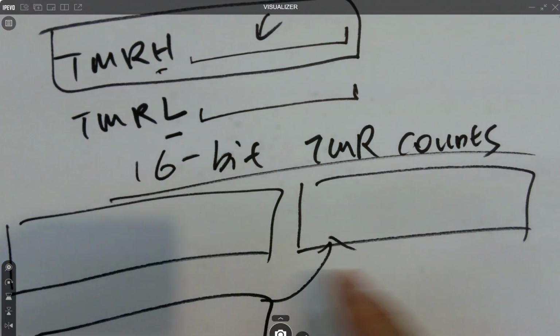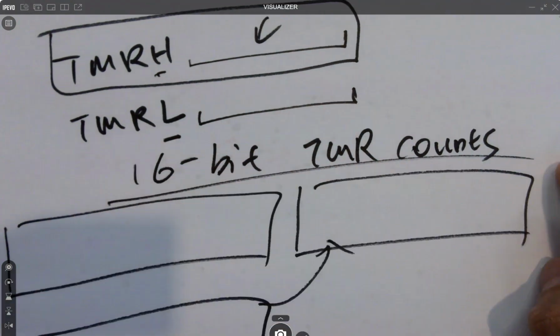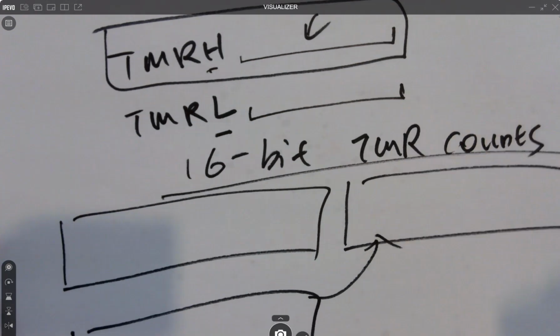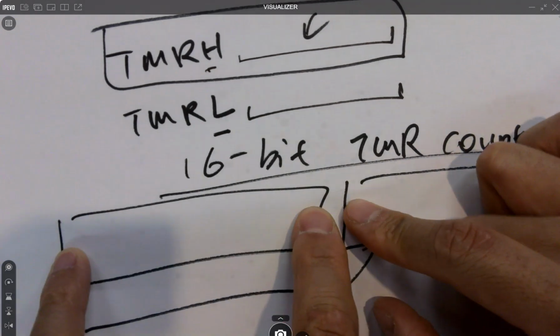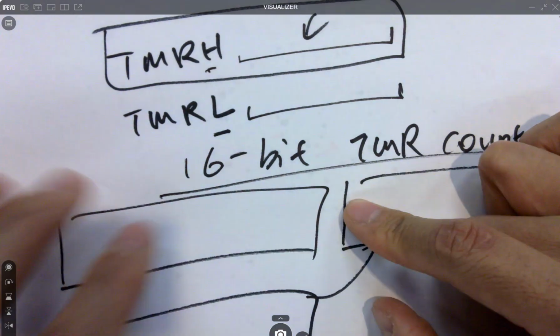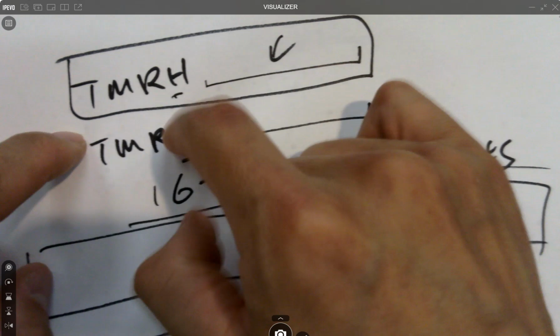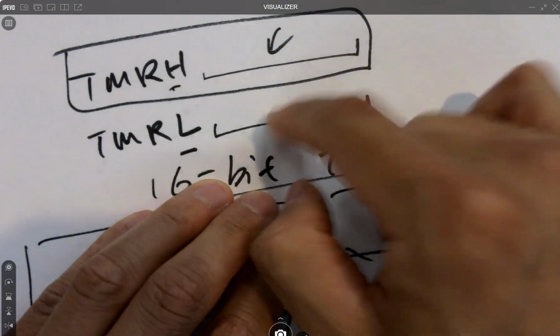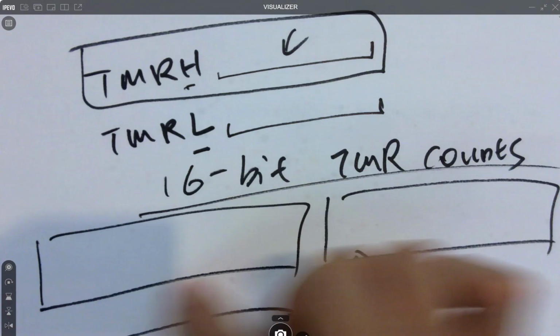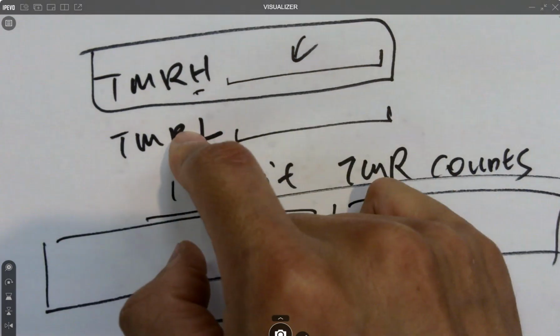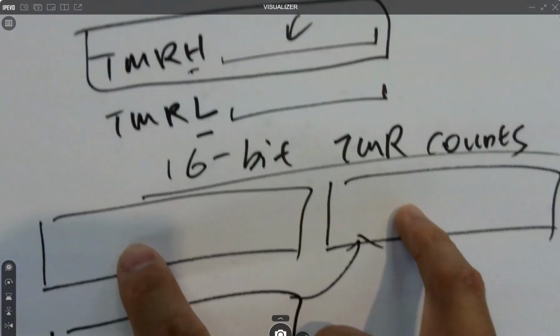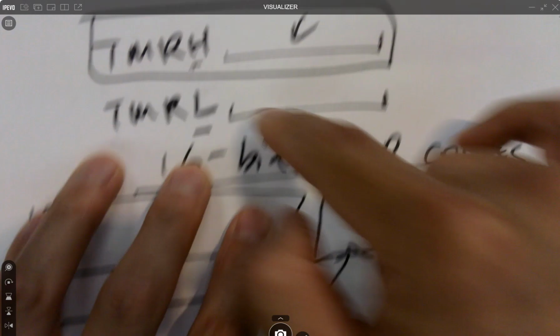So what's happening is you do the shift for the first step to get the higher byte out and put it in here. And the second time you directly give this 16-bit number to this register. So only the lower byte will be stored in this variable, but the rest will not, because this one is only one byte, and this is longer than that. You know what I mean? Only the shorter part will be stored in here.